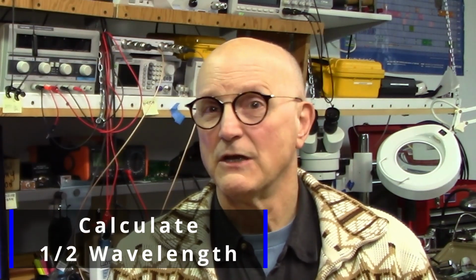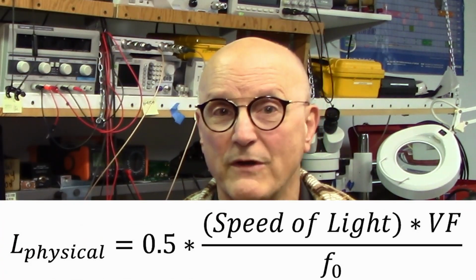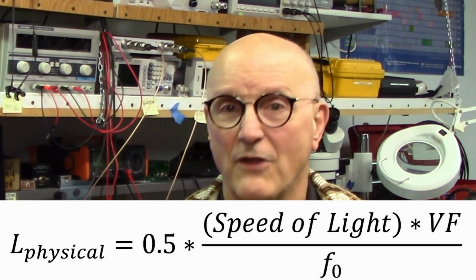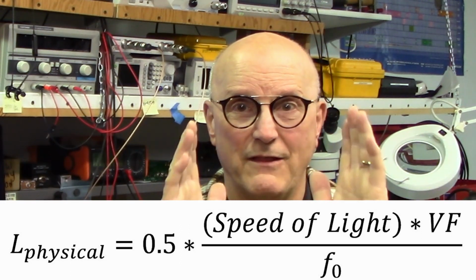The design all revolves around 1/2 wavelengths of coax. So our first step is to calculate what these lengths should be. To do this, we use the following formula. The physical length is equal to 0.5 times the speed of light times the velocity factor, all divided by the frequency in question, where the speed of light in free space needs to be in whatever units make sense for you. The units that you choose for the speed of light determine the units of the physical length that you calculate. I have provided the value for the speed of light in inches per second and centimeters per second in the description below for your convenience.